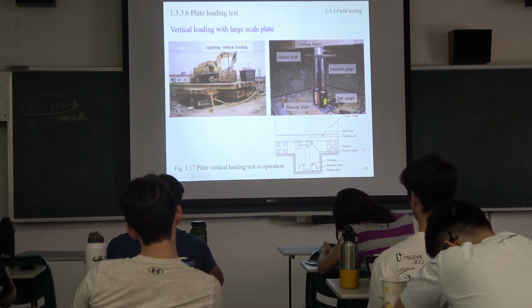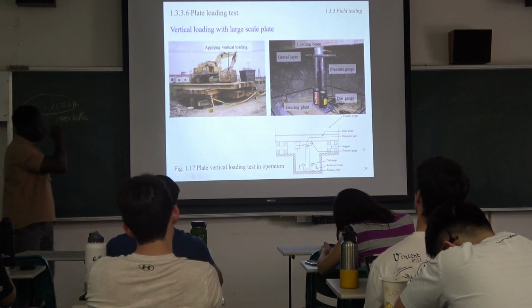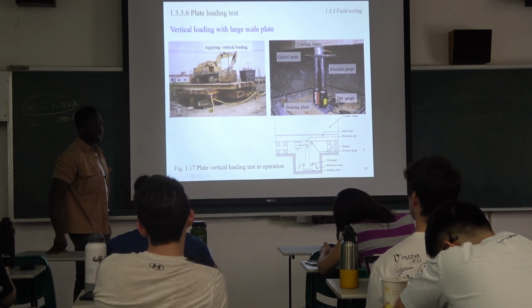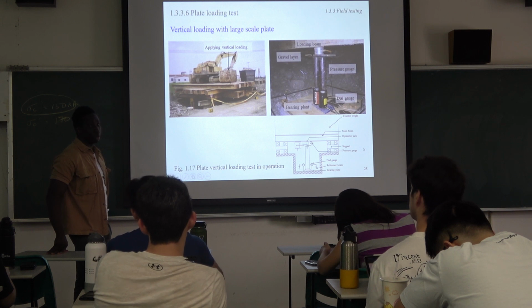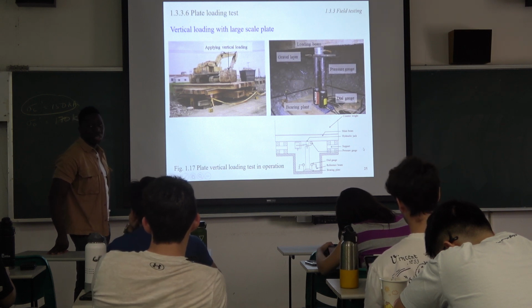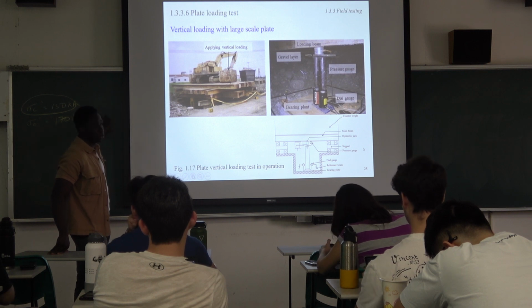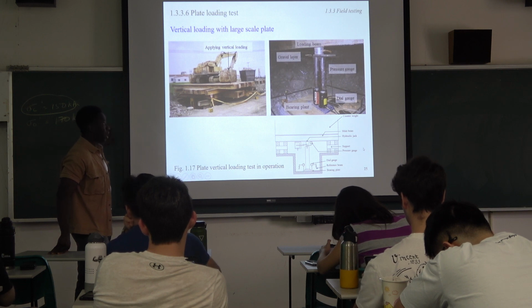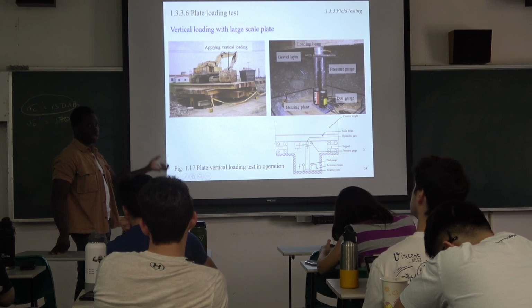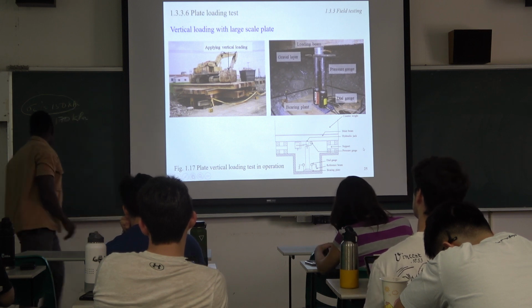And for this test, not only can it help you to determine the ultimate bearing capacity, but it can also help you to determine the settlement. Because every time you apply some sort of loading onto the soil, it will settle. For example, when you apply 1,000, you can see the soil doesn't fail, but how much does it settle? Let's say this is the original.